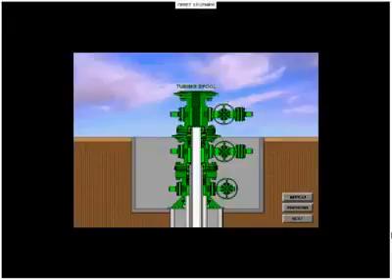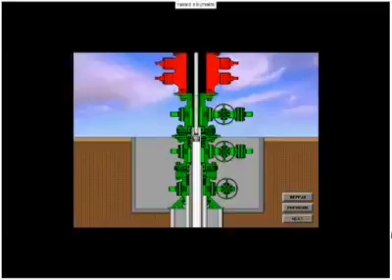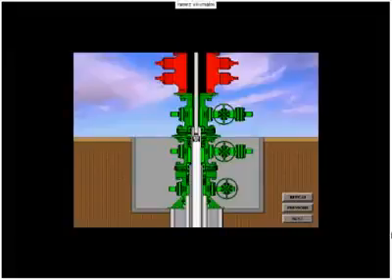The tubing spool with a crossover seal is installed in the same manner as the casing spool. After the tubing spool has been installed, the seals and connection are tested, and the BOP system is nippled up. Preparations are now made to run production tubing in the hole. Production tubing is considered any pipe string 4 inches in diameter or less, though sometimes larger sizes of pipe are used.